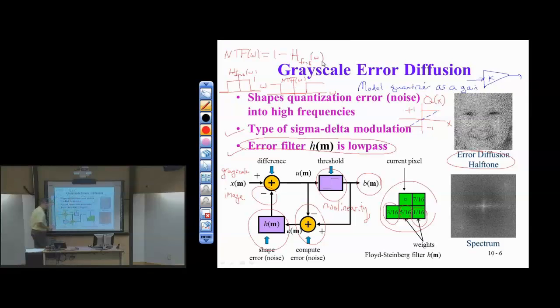Okay, the signal transfer function is a little more complicated. Again, the noise transfer function is obtained here by replacing the quantizer with additive noise. So for the noise transfer function idea, we're going to replace the quantizer. Again, remember, the quantizer can be viewed as adding some uniformly distributed random variable to the input. It's a random error in the output.